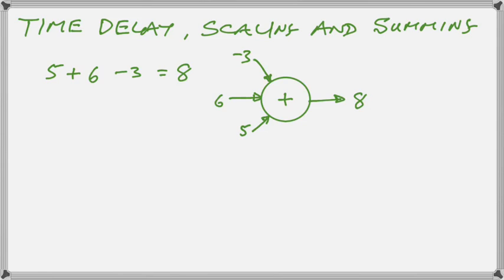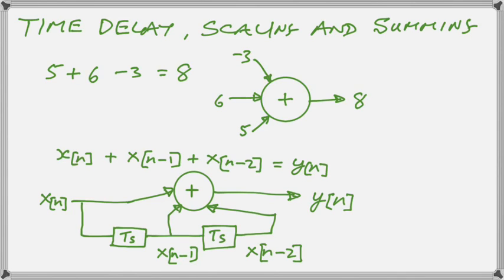Now let's take a look at the time delay. Each of those blocks marked TS delays what is on the left side for a specific amount of time, the same amount of time. Basically, TS is the sample period. So it gets an exact time delay mathematically and digitally, so that what comes out on the right is just slightly displaced from what went in on the left.